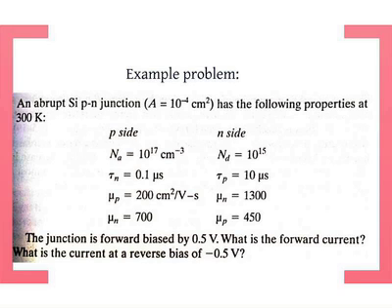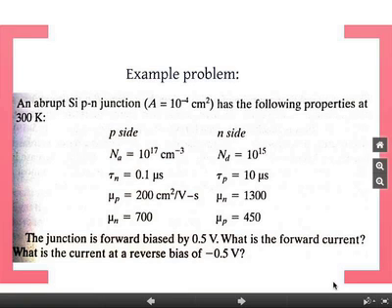So just make sure you follow the logic again. You look up the equations. You don't need to memorize any of this. So for half volt forward bias, you get the answer here is about 1 microamp, and in reverse bias, again you do the same thing. You plug in minus 5 volts, and you see the answer is about 10 raised to minus 15 amps. So it's very, very, very small. Okay, this is what you expect for a good diode.